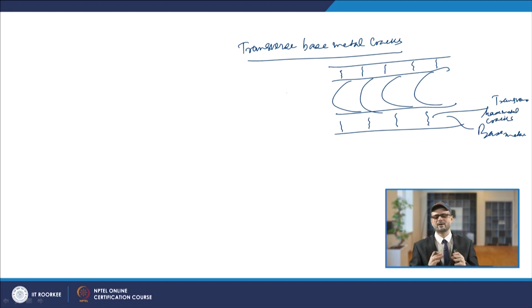They are developing perpendicular to the weld axis. As you see, this is developing perpendicular to the weld axis, and normally they are associated with the welding of high hardenability steels. So, normally when you weld tool steels or certain alloy steels which are highly hardenable, in those cases these kinds of defects like transverse base metal cracks may occur.